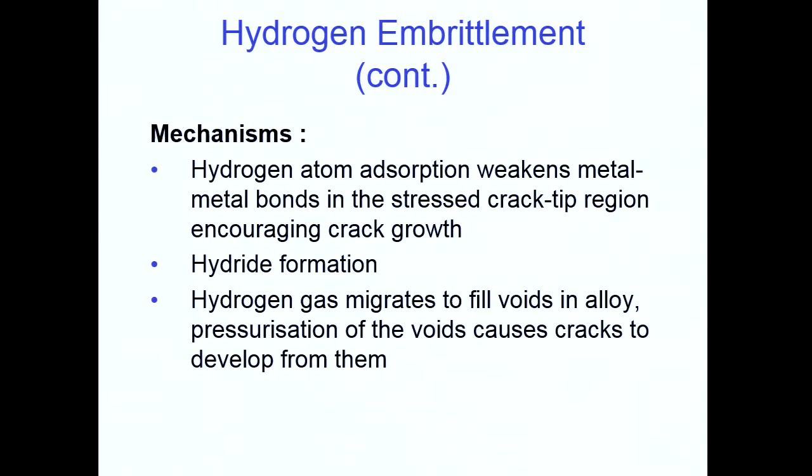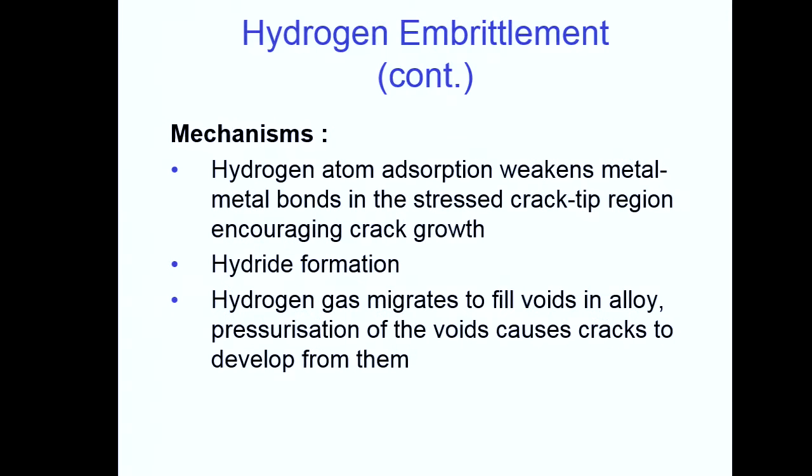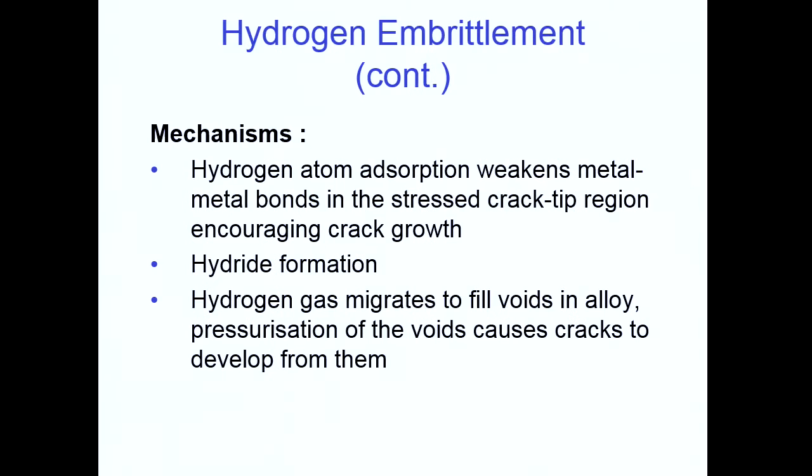And I don't know whether you can see it at the top here, but the specimen seems to be bowed. It's sort of swelled up, particularly in this region here, and that's because you've got more and more hydride there. The point of entry for the hydride was here. It was actually a spot weld on the material, and that was a good place for the hydrogen to get in and start to attack it. So there's definitely a mechanism for hydride in some metals, but not steels.